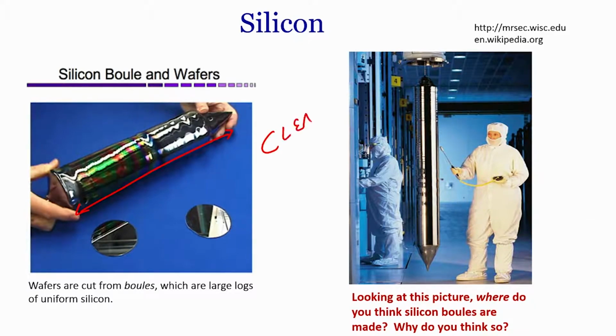Within the clean room there are several classes of clean room, starting from class 1 to 10 to 100 to 1000 to 10,000, to 100,000. Depending on what kind of fabrication of sensors or actuators we are going to do, we can use that particular class of clean room.